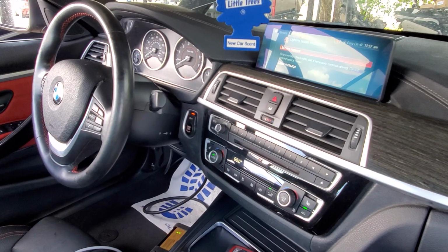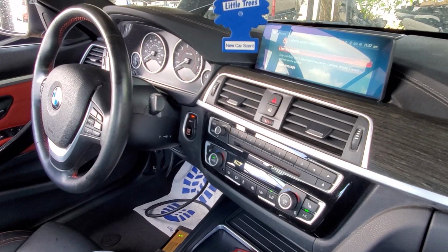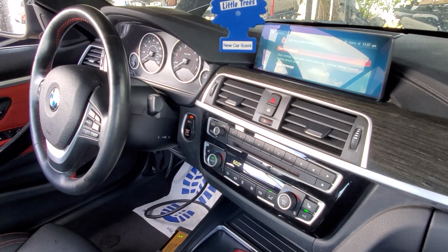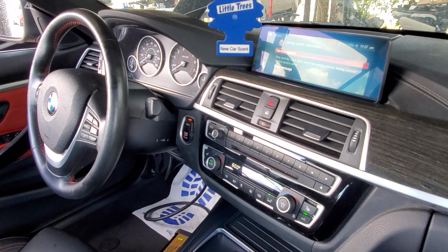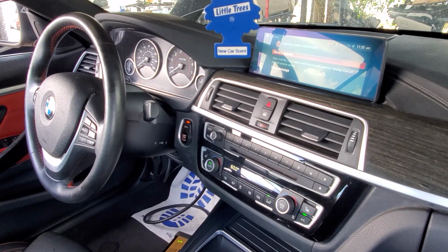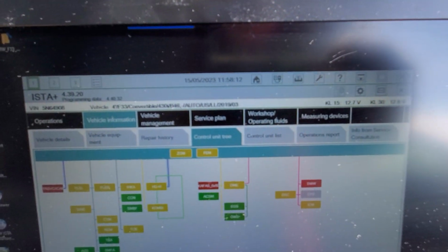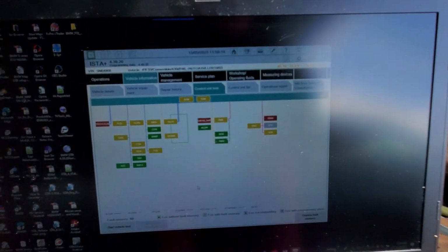The startability threshold is basically 12.5 volts, or 12 volts. If it drops below that, it's going to turn off the ignition on its own if it senses that the ignition is on and the diagnostic socket is not being used. But if you have the battery maintainer on the car like this, and it's at 12.5 volts, and you turn on ignition, it's not going to turn it off. You just want to make sure that the voltage is not dropping below the startability threshold.